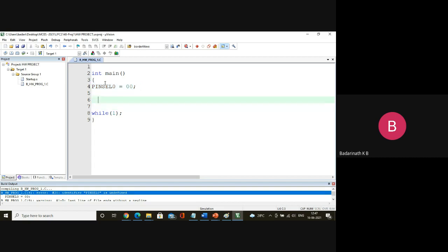So how can a normal C program understand this? I can include standard stdio.h or conio.h. Those will support only standard C functions. But none of the functions already provided as a part of the classic C libraries support the details of the microcontroller inside. So whenever you purchase a microcontroller, the manufacturer always supplies a header file corresponding to the microcontroller. That header file you should include in the project.